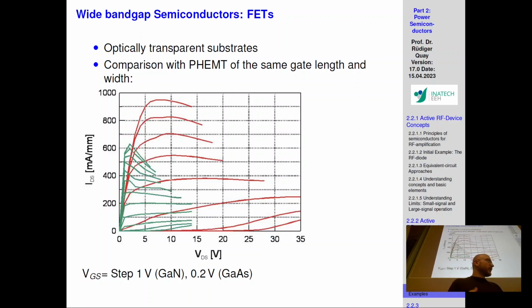Power devices aren't really done at 1 terahertz. You don't do power devices there. You try to do low noise amplifiers, and you reach the higher power by having diode multipliers. And at some point, you use optics, lasers, and so forth, or tunneling amplifiers, to get the required power.